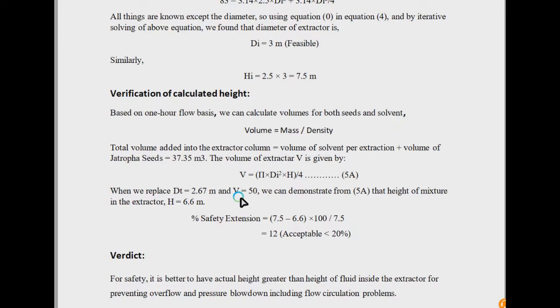The same can be said for the design calculation of the evaporator. That is actually a simple bit. I have only considered a plate type. In the case of a plate type, there are no tubes, no specific internals, no baffles, no tie rods, no spacers, nothing else like conventional shell and tube type or double pipe type. Double pipe is actually simple, but a plate type is much simpler. So the evaporator based on a simple plate type will only follow the calculation defined above.